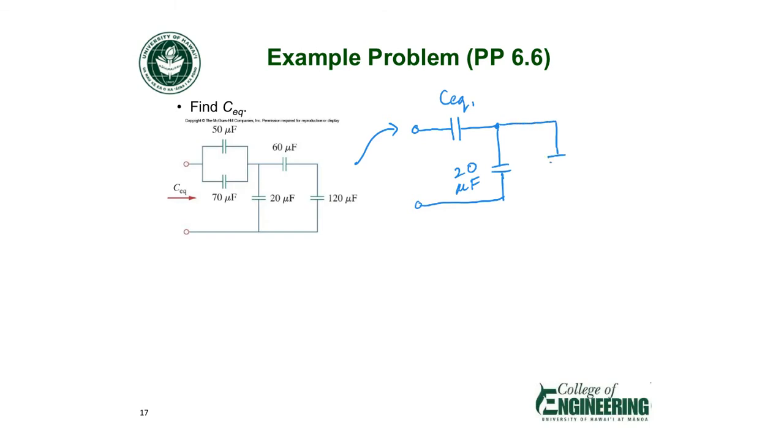And then I'm also going to combine the 60 and 120 microfarad capacitor in series to another capacitance, CEQ2. Everyone okay so far, right? This is just like resistors.